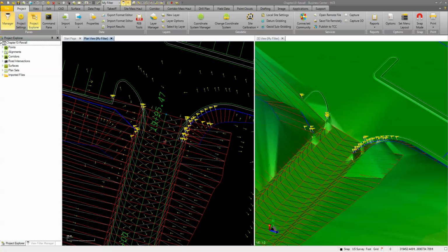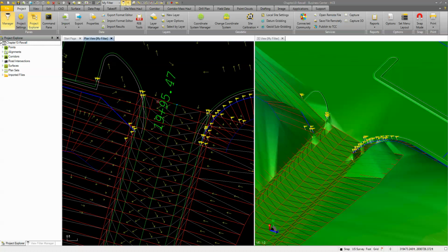I'm going to start by moving the corridor back to this segment here where my curb returns come back, and this is where our curb will end. Then we'll get into just a shoulder and a ditch within the corridor that will tie in with some ditches. So I'm going to go to the corridor, go to the main road, and add a transition in here.